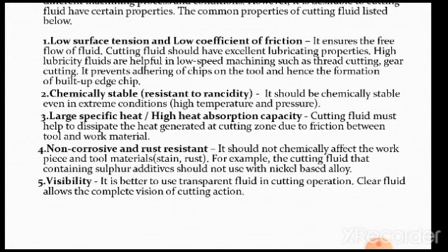Chemically stable means what? That the cutting fluid composition should be in such a way that it should not react either to the workpiece or to the cutting tool, thereby reducing the cutting efficiency or hampering the machining process.